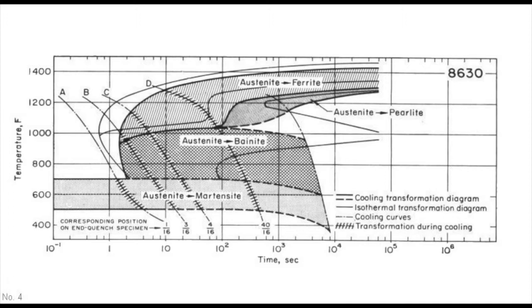Austenite has a high solubility limit of carbon, so a high concentration of carbon will diffuse into the surface of the shackle, which would be up to 0.7 weight%. The shackle would then be quenched in water to form BCT martensite at the surface. However, the surface would also be very brittle due to the martensite, so tempering is then required. The shackle would then be tempered to 200 degrees Celsius for between half an hour to an hour to reduce some of the brittleness of the surface while not sacrificing too much hardness.